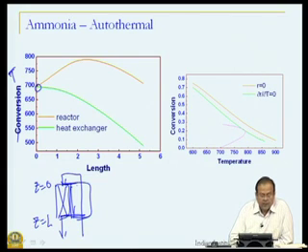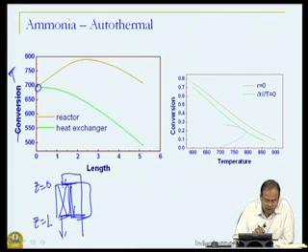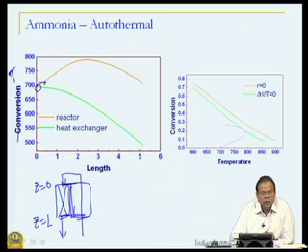That means a little further down in the reaction, the heat exchange rate at the inlet is 0, because there is no driving force, but there is a reaction there and the reaction is generating energy. So, initially the rate of heat generation will exceed the rate of heat transfer and the temperature will slightly increase, okay, in the reactor.